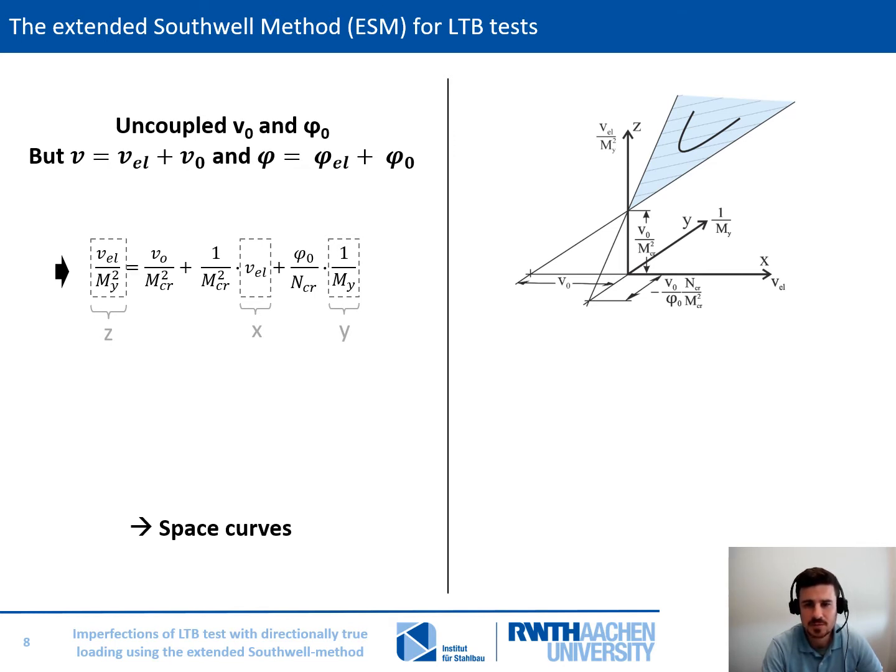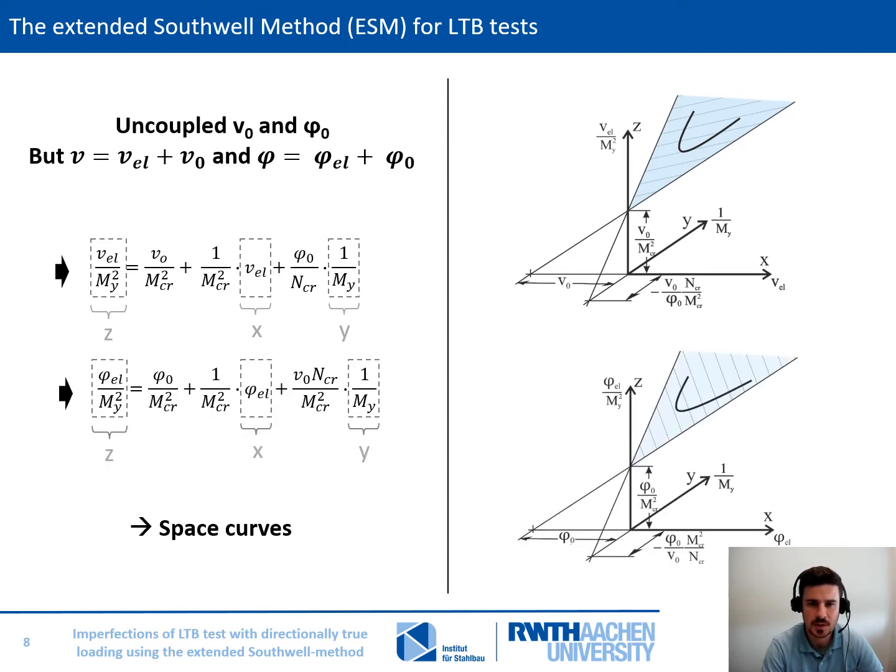The values v, L and mu are from the experimental data. Of course, we can use the same procedure for the rotation phi. With these relationships, an extended Southwell plot can be found.